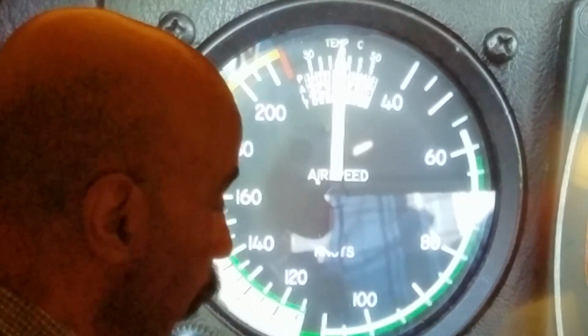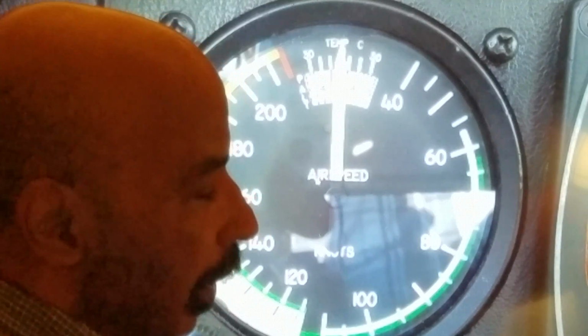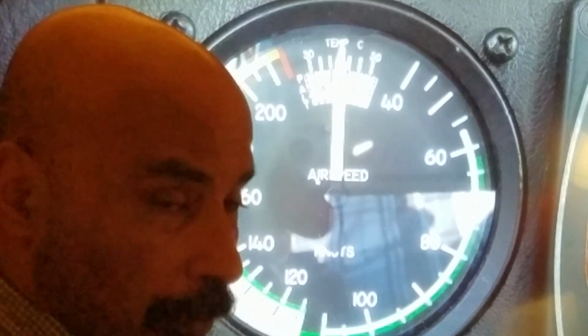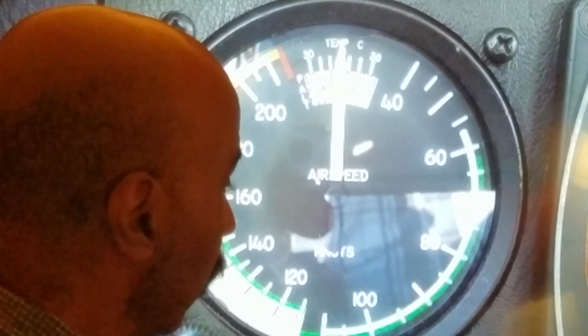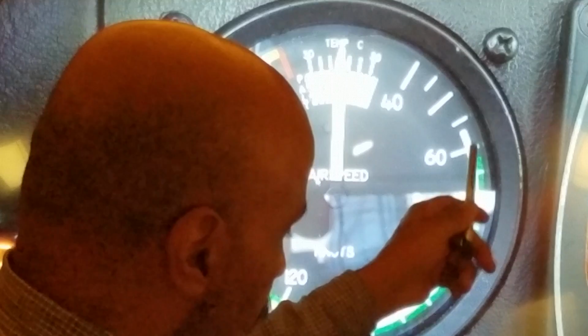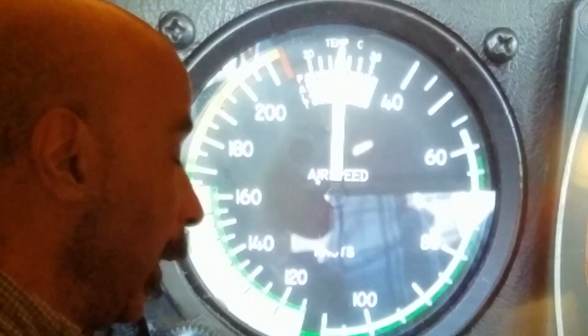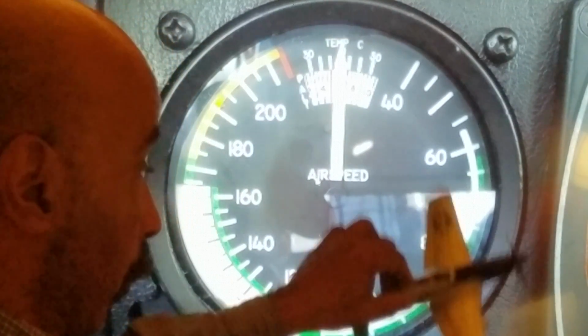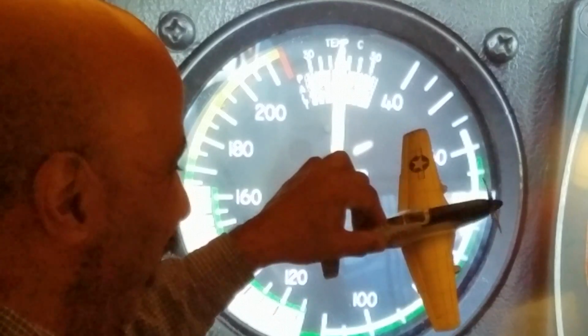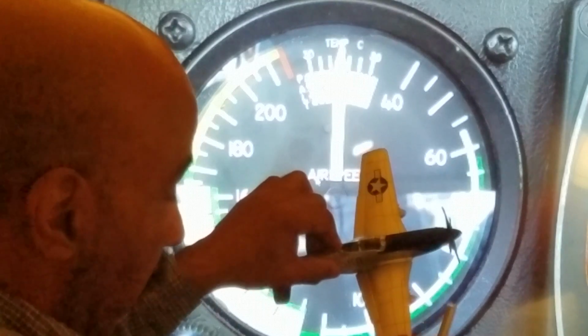And I have not gone to the POH, Pilot Operating Handbook, to discuss maneuvering speed. They really should indicate a mark for maneuvering speed on this airspeed indicator, like they do these arcs here. Maneuvering speed is a speed where you can yank the controls if you were flying and let's say you were in a dogfight. Or if you just wanted to do an accelerated stall during normal pilot training.